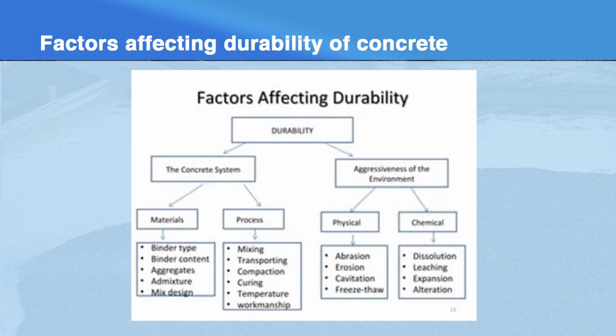This includes resisting weathering, chemical attack, seawater attack, abrasion, etc. Now, different concretes require different degrees of durability depending upon the exposure and environment and the properties desired. For example, the concrete which is exposed to tidal seawater will have different requirements than an indoor concrete.